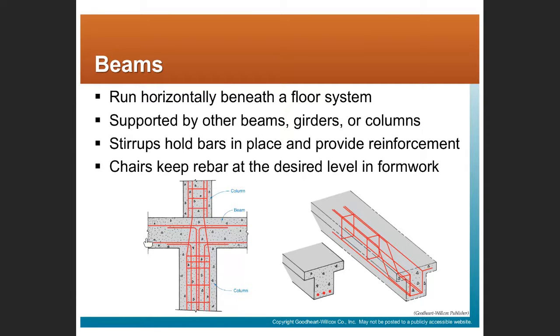So again, this would be the structural engineer's business to figure all that out and detail it. Right? The structural engineer is the part of the design team that's going to be responsible for designing these structural systems to hold the building up. The architect will say, hey, I need something that's going to bear this much weight, 150 pounds a square foot. That's my design live load. So Mr. or Ms. Structural Engineer, you figure it out and make it as economical as possible so we can deliver this structure on the budget that our client is looking for.